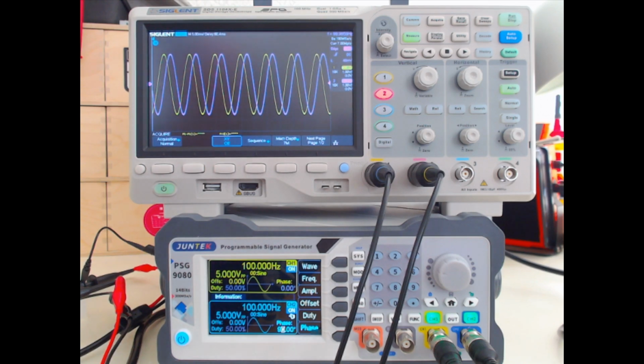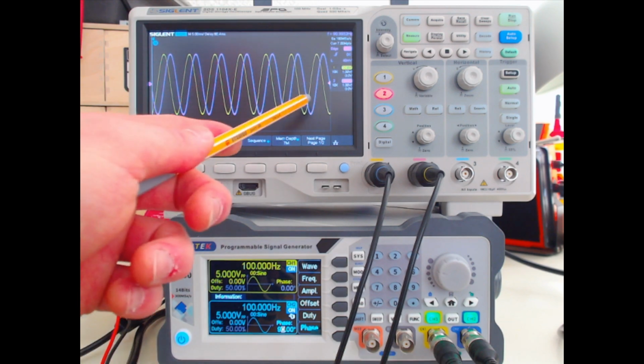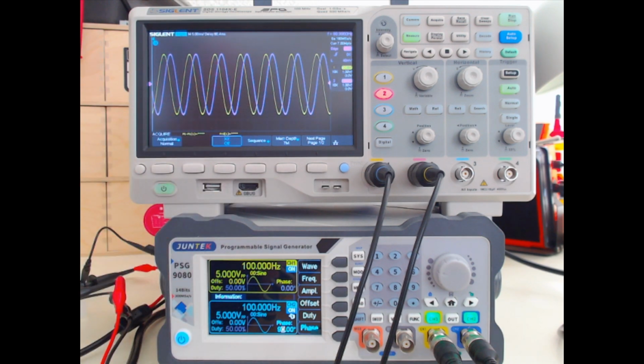Okay, so to understand what's actually going on in this XY mode, I've brought out another piece of equipment. This is a function generator or signal generator, or an arbitrary waveform generator, you might also hear it called. Basically, this is something we can use to generate signals that we can plug into the oscilloscope or other kinds of equipment. In this case, I want to give us some example waves that we can manipulate and see how they respond in XY mode.